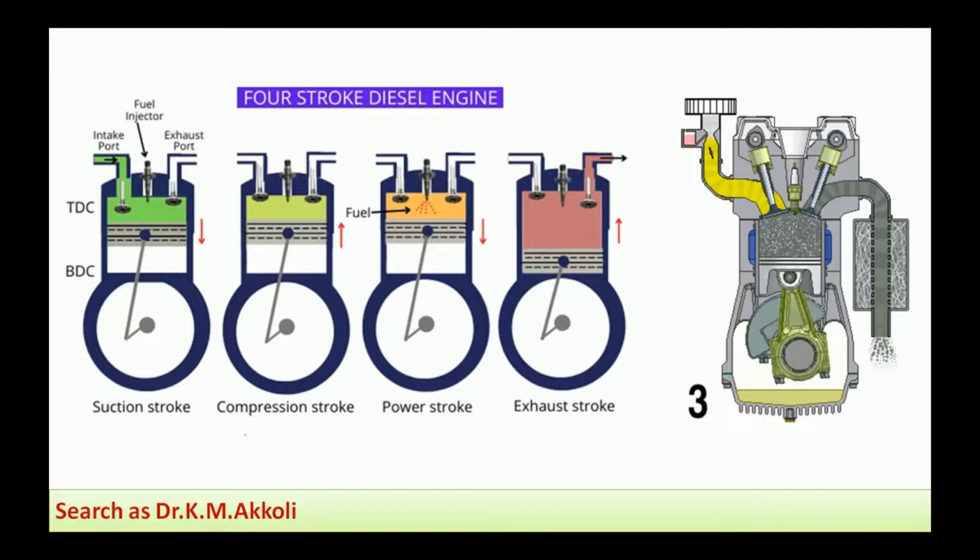Instead of the spark plug there is a fuel injector, and this is the connecting rod, crankshaft, and crank. The extreme position towards the cylinder head is the top dead center, TDC, and the extreme position towards the crank end is the bottom dead center, BDC.